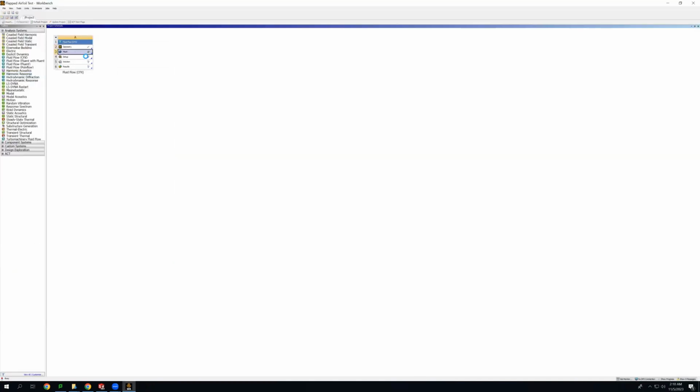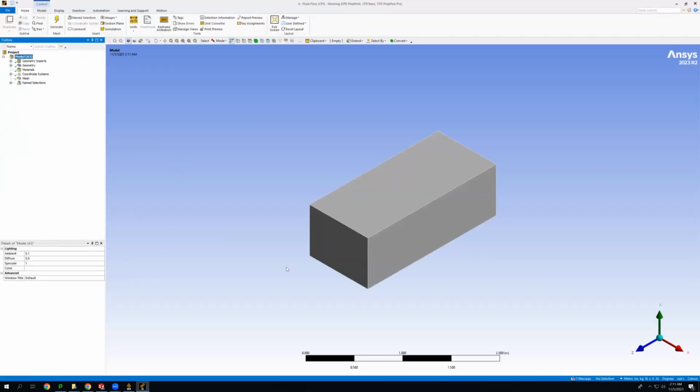After you've done that, refresh your mesh. The arrow symbol here is used to indicate the mesh needs to be refreshed, so it knows what has been updated in your geometry before you can load the mesh editor. And once you see the lightning icon, you can edit. Right-click and then edit. It's going to take a while to load. But once it is, and you see this rectangle here, you can generate your mesh. This little green lightning icon here means that it's currently meshing.